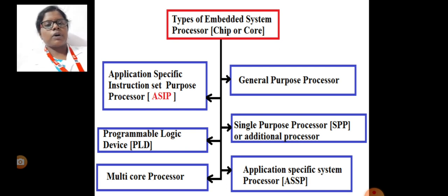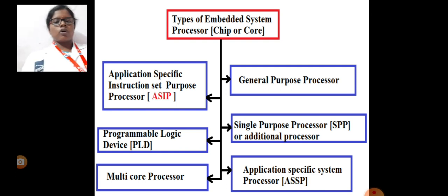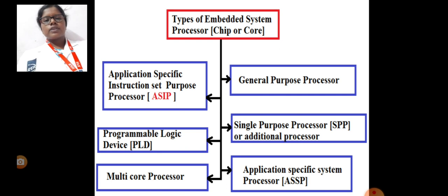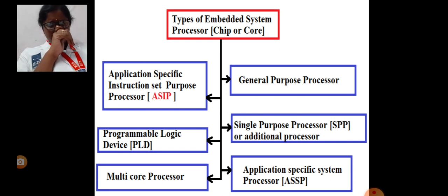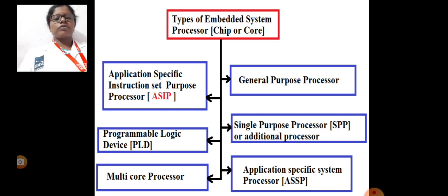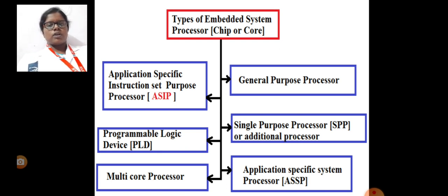First one is power supply. An internal power supply source or a charge pump is essential in every system. An embedded system has to perform tasks continuously from power up to power off. It may be kept on continuously. Own power supply system: various units in an embedded system operate in one of the following four operation ranges. Maybe 5 volt plus or minus 0.25 volt, 3.3 volt plus or minus 0.3 volt, 2 volt plus or minus 0.2 volt, and 1.5 volt plus or minus 0.2 volt.